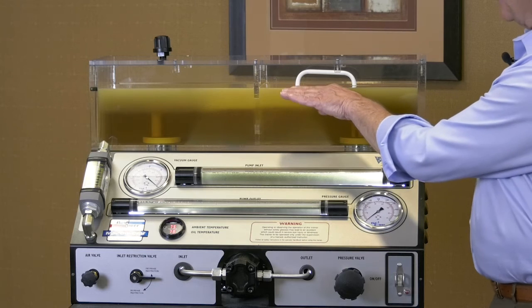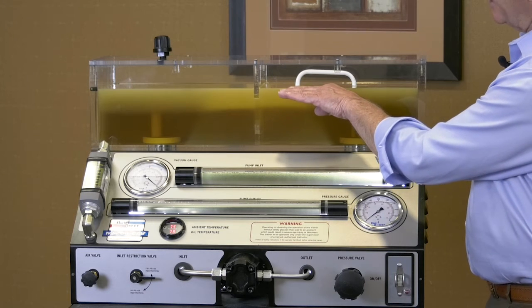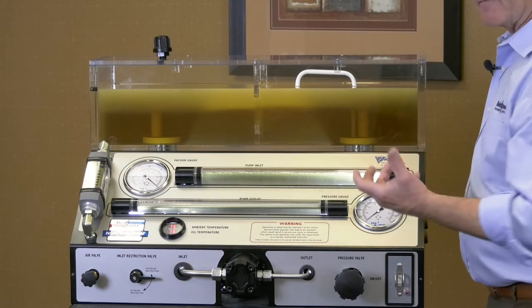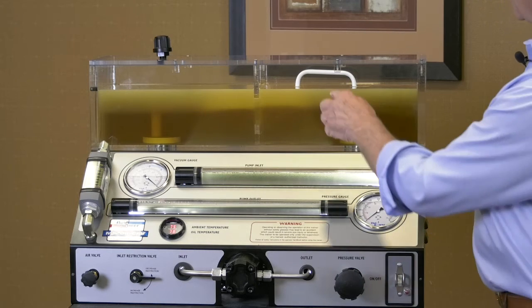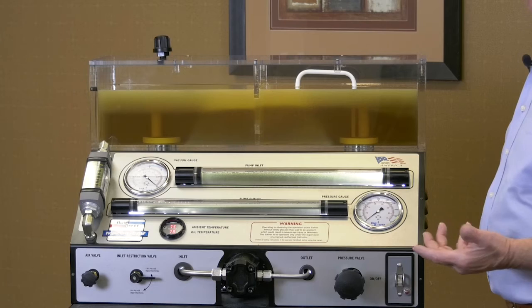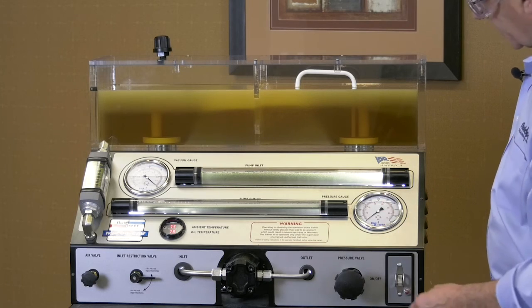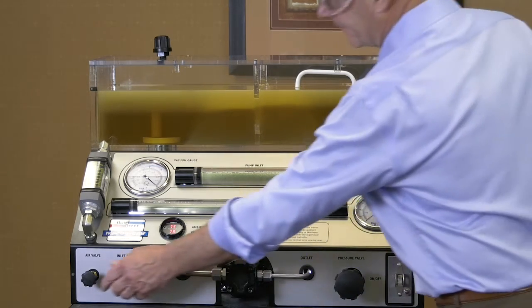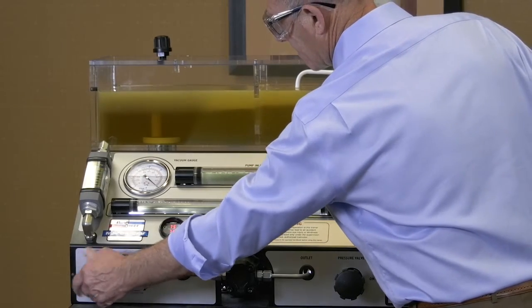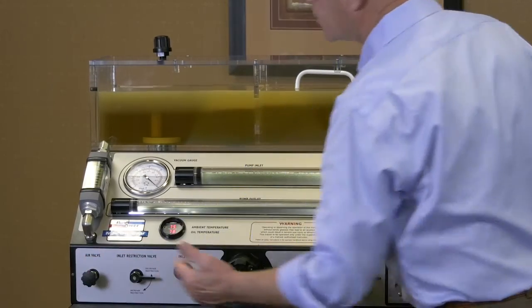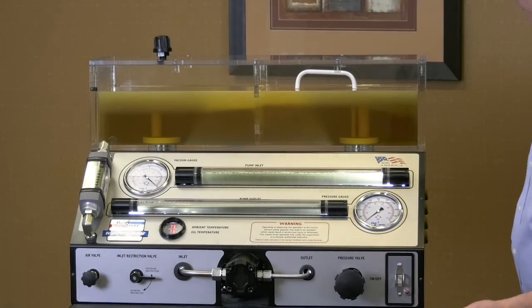Now I'm going to let it gradually lower, because I've opened the valve and I'm draining the oil out, and in a moment the return line will be above the oil level. So I'll start it up. I've closed off the valve that lets the air go in.